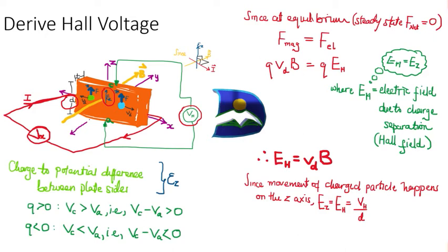So if you divide your Hall's voltage by that of the width of your material, you will get the electrical field. So in this particular case, in conclusion here, we have this particular expression which we derived from the equilibrium state. Put that into your charged particles' electrical field, and you will get your expression in terms of the drift velocity.